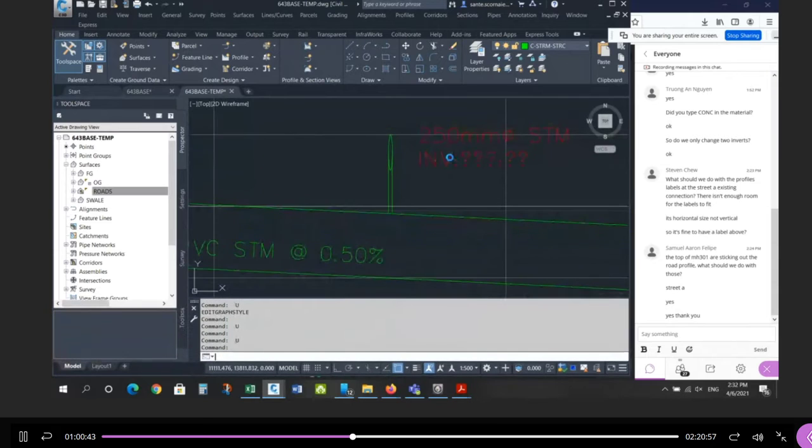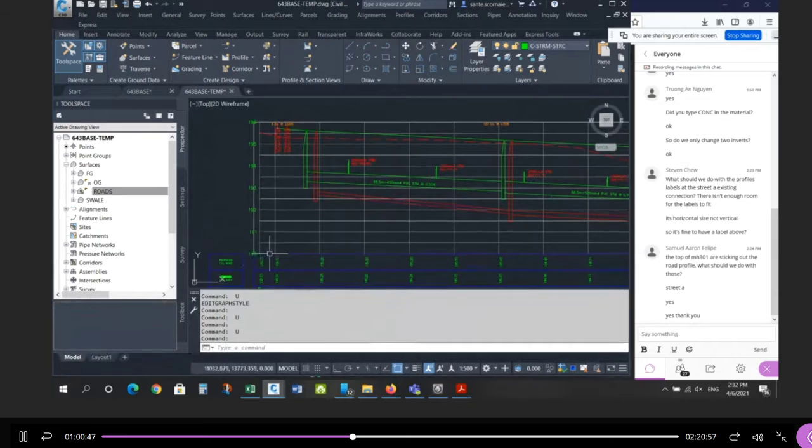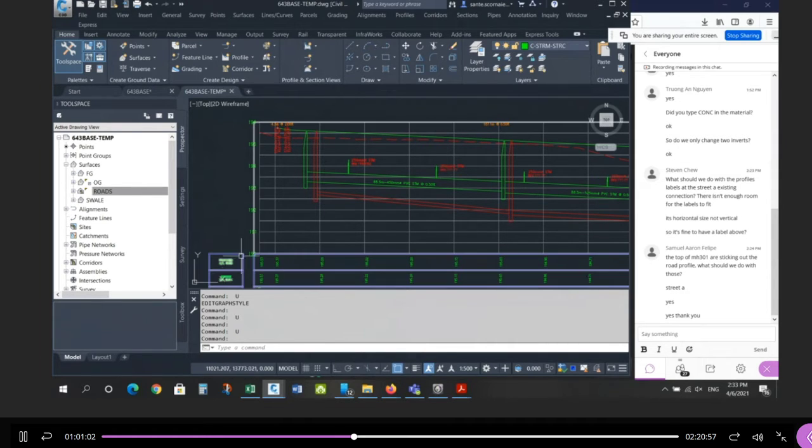Okay, so you have to make sure anything you draw manually, if you change the bottom elevation of your grid, or if you change the vertical exaggeration of your grid, you have to redraw anything you did manually. And that's a bit of a pain. Okay, so you want to establish scale and elevation. The vertical shift for changing the elevation of the bottom is not as difficult a task as changing the vertical scale, where you have to either stretch or squash stuff based on the new scale.